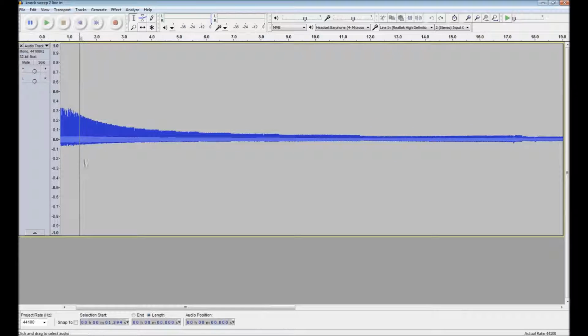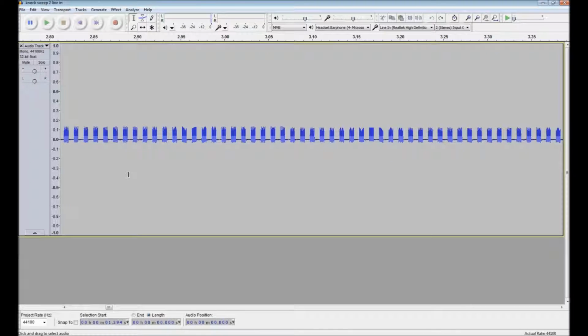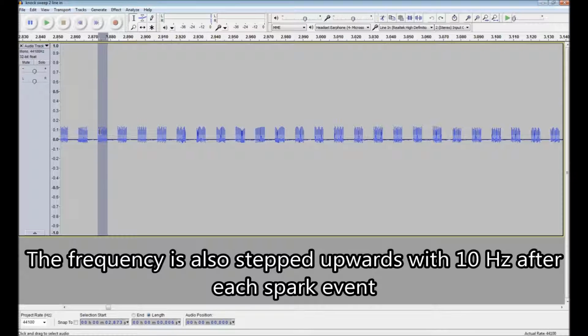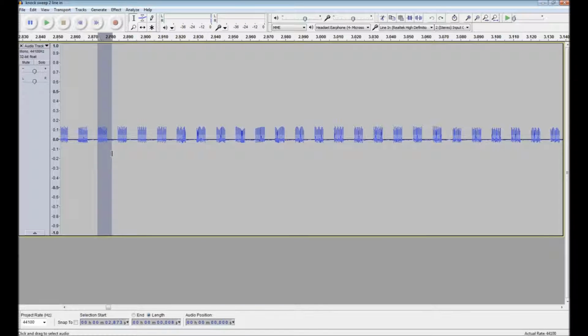We can zoom in and look at the individual pulses that are sent to the ECU. So when we send this pulse, it's 6 milliseconds long. This is sent right after the ignition event took place. So this is not a random send, it's an actual send to trigger the ECU to detect knock. And the total length is 12 milliseconds. This is because we run at 4100 RPM, so we can detect up to 15 milliseconds per RPM and event.